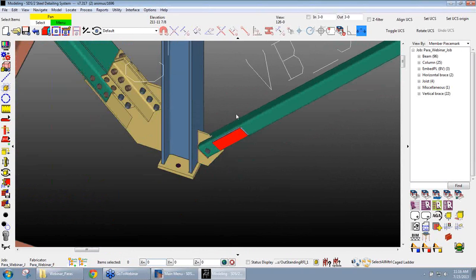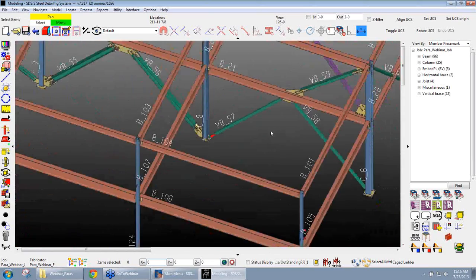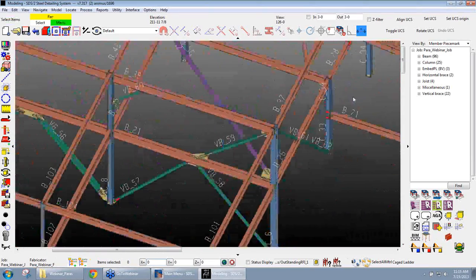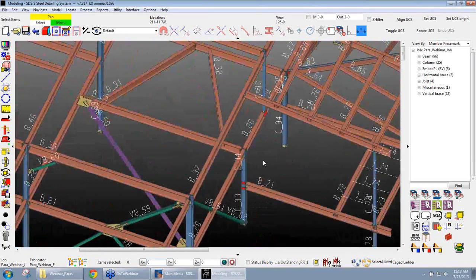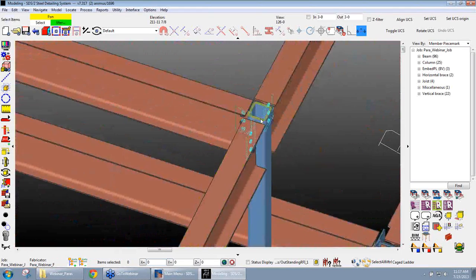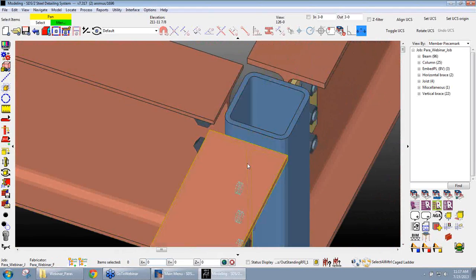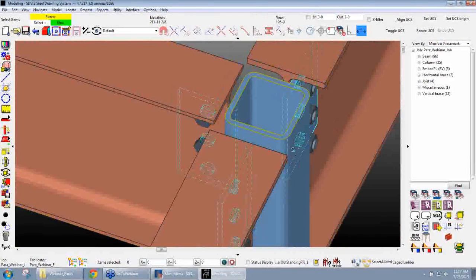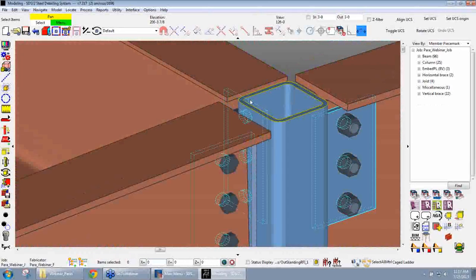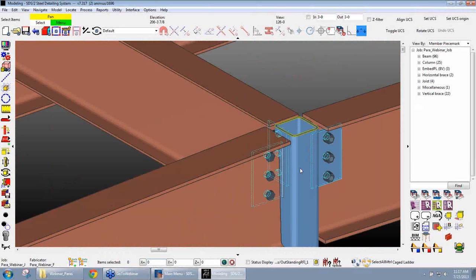From here, moving on, there are different times where I've heard of scenarios where we need to go through and put bevels on all four sides of an HSS piece of material. Maybe you're getting some type of weld prep, full pen weld there to a cap plate or anything else. I'm just going to use this particular example for this HSS material here. I want to add in bevels to all four sides here. Now through your end preps, there's really not a way to do so on that one.